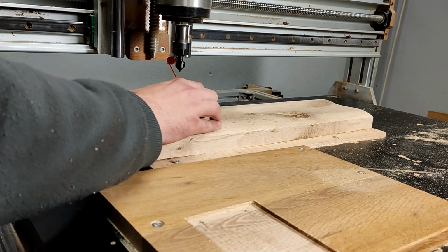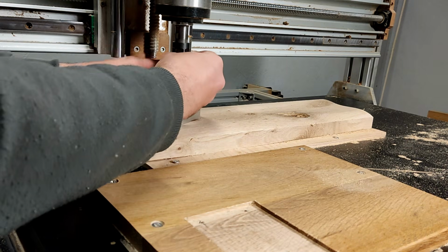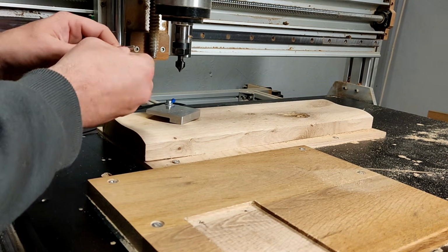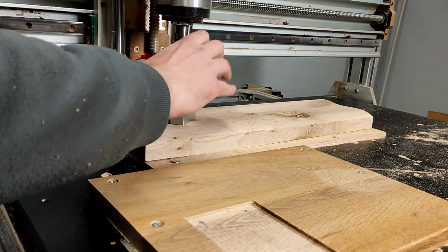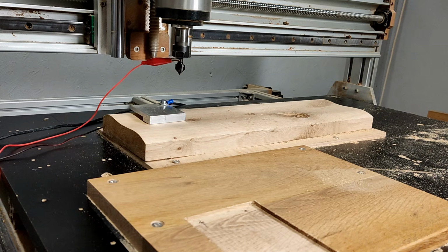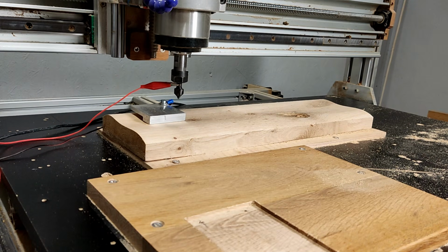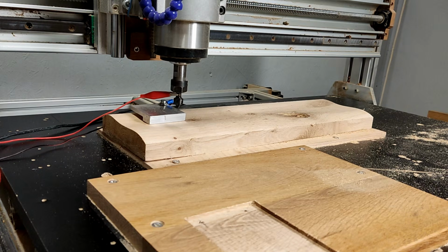Make sure the cable is correctly positioned so it doesn't snap off the toolbit. Otherwise, if this happens during probing, you will end up with the toolbit going through the touch plate, and this is not going to be a good thing. Now let's lower the spindle. Bring it pretty close to the touch plate.